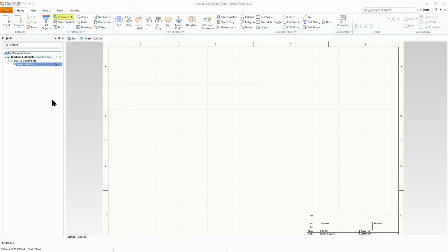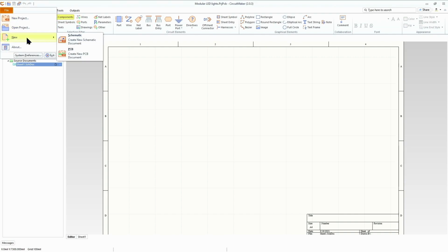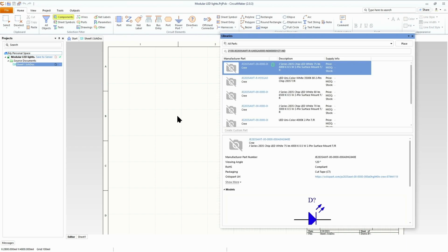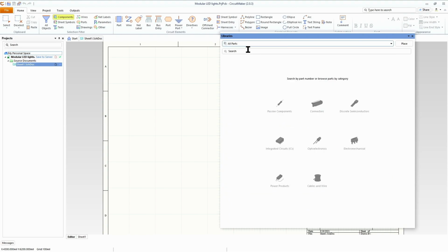So it's very easy. Just start a new project, go up to File, and then New Schematic, which brings you to this view here. Now, one thing about designing with this particular program, it may be true of other programs as well, but it really makes things easier if you know exactly what components you're going to be using. If I press C on my keyboard, it'll bring up the component selector, and you can have a favorites or just from all parts that it has a library of.